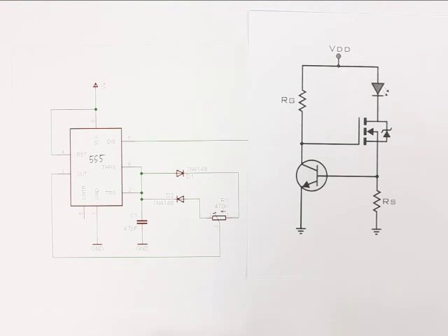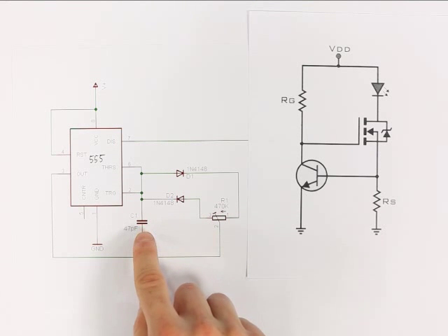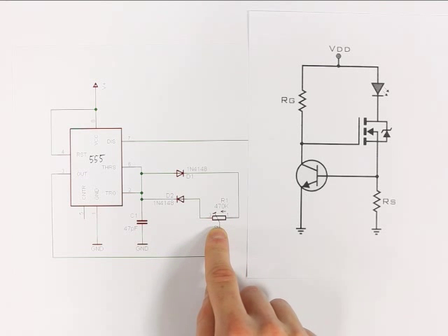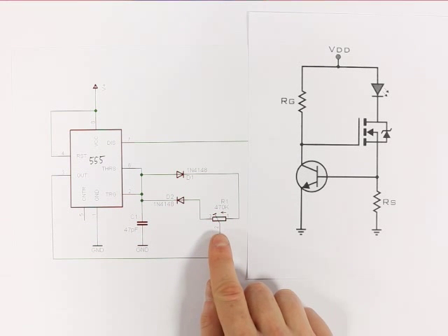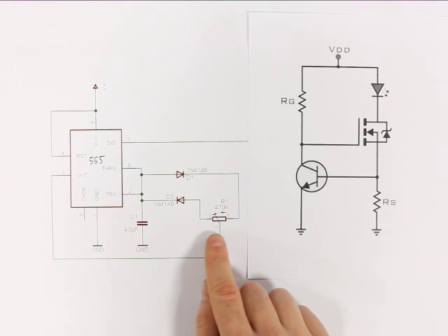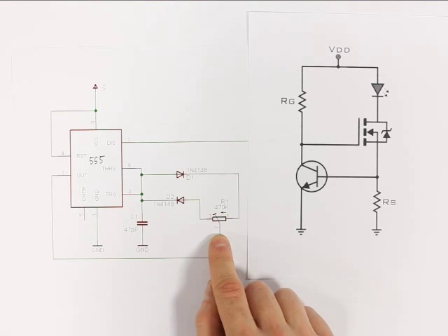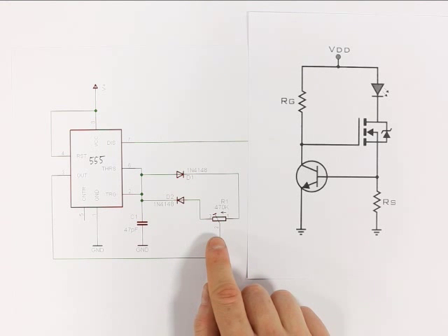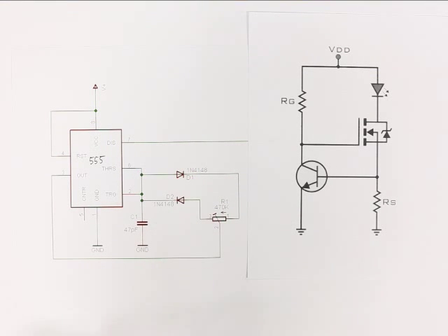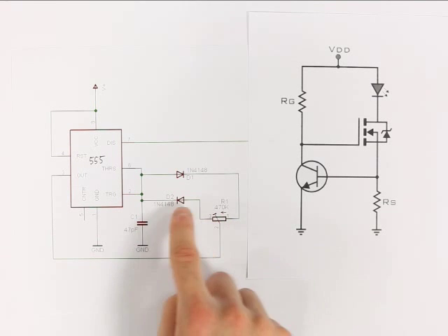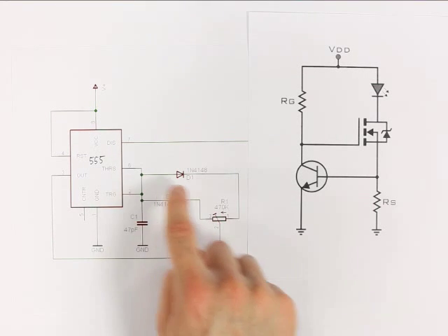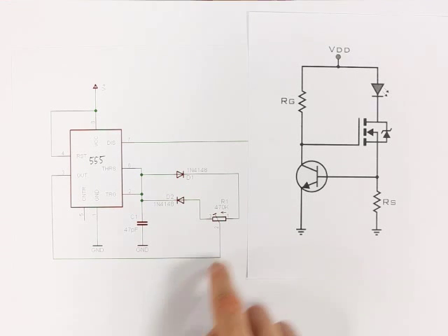Before I do that though, one thing I'll just mention, some of the components I'll be using in this circuit, aside from the capacitor you saw in the previous example, this circuit has a trim pot potentiometer here, which is an adjustable resistor with 3 terminals. It acts a little bit like an adjustable voltage divider, and then a couple of diodes which connected to the same pins at this end just ensure that current doesn't just flow through the easier route in this potentiometer. It always goes the same direction.